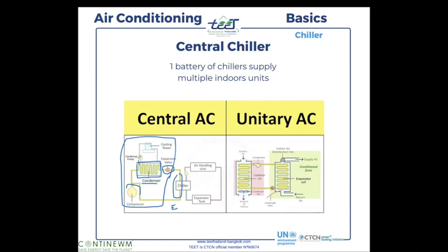And we have a system to cool the refrigerant fluid in the condenser with water. Instead of being cooled by air outside, we cool it with water, okay? And the water is circulated to a cooling tower, so we cool the water that cools the refrigerant. So we have a heat transfer, basically.